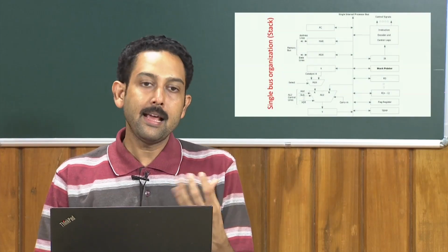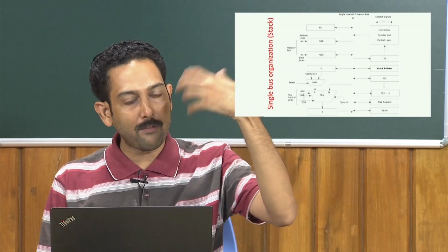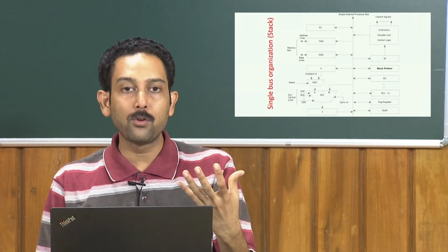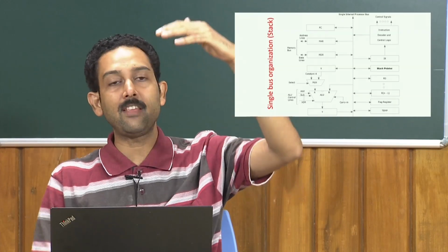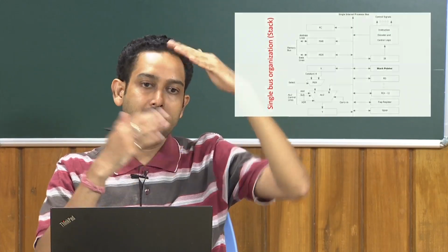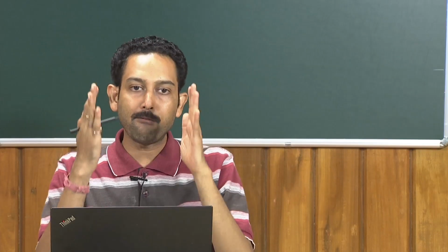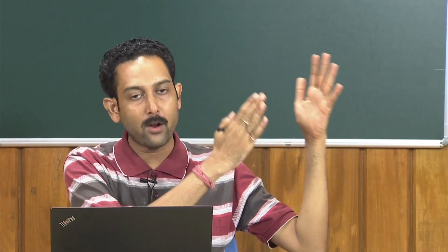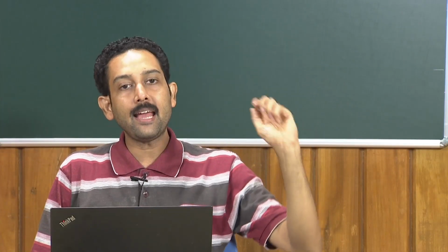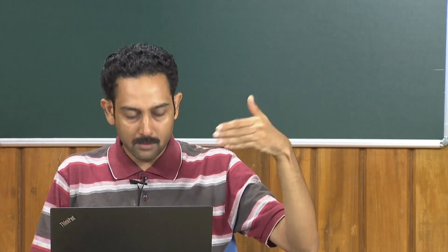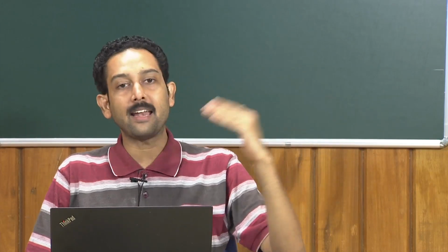So, every time we jump to a function or an interrupt service subroutine, what do we do? We save the value of the program counter and the values of all the intermediate registers and everything we are doing in one function to a temporary scratch pad or temporary memory, go and service the interrupt or finish the procedure, and then come back and take up all the values of the temporary registers which we have saved and start executing.